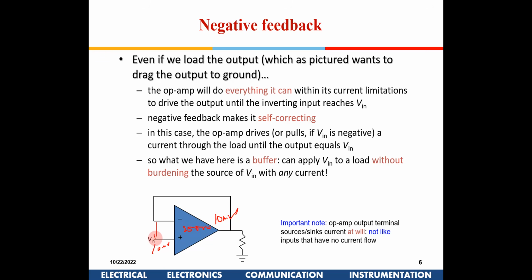So this difference VD will be 10 millivolt divided by 20,000, right? That is very, very small. So you can assume these two voltages are almost following each other. That way also we can think.